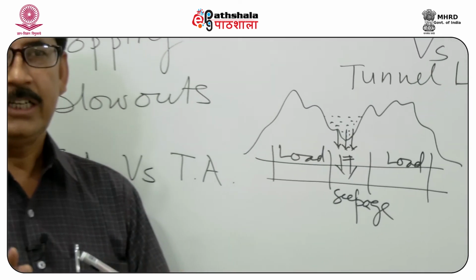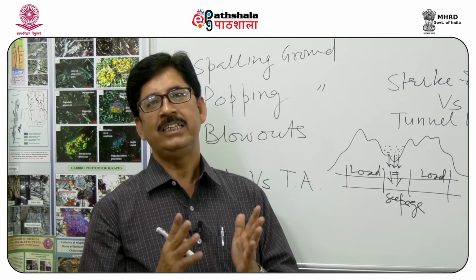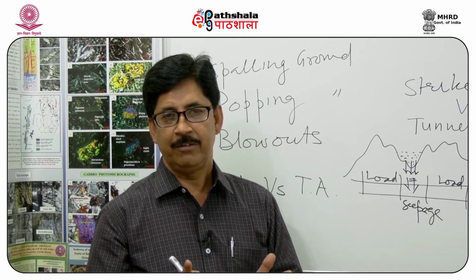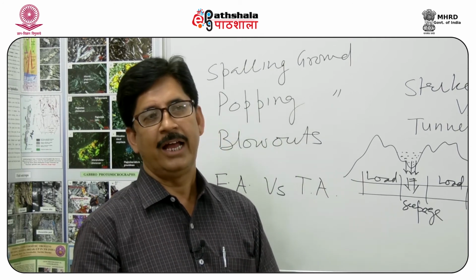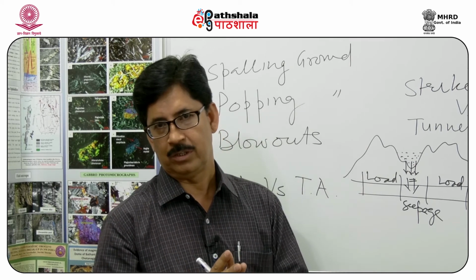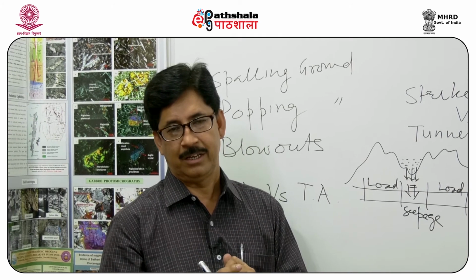Now if we make tunnel along the anticlinal axis, then because the anticlinal zones are under tensile stresses, we'll have a lot of fracture system and it will be easy to drive tunnel through the anticlinal zone. But we may need a lot of support.